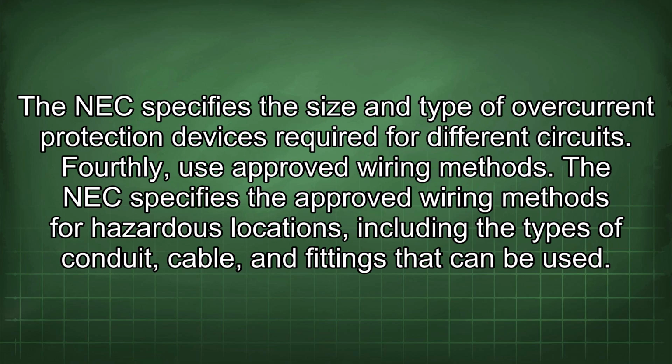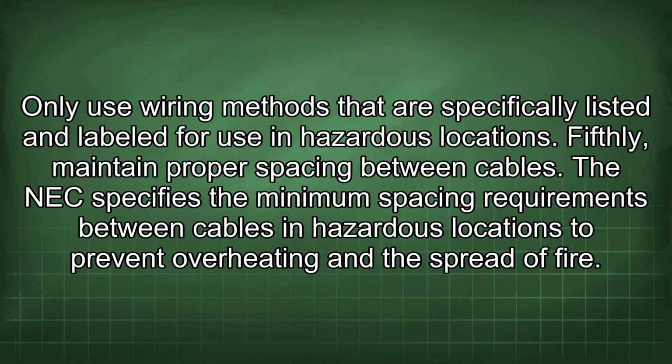Fourthly, use approved wiring methods. The NEC specifies the approved wiring methods for hazardous locations, including the types of conduit, cable, and fittings that can be used. Only use wiring methods that are specifically listed and labeled for use in hazardous locations.